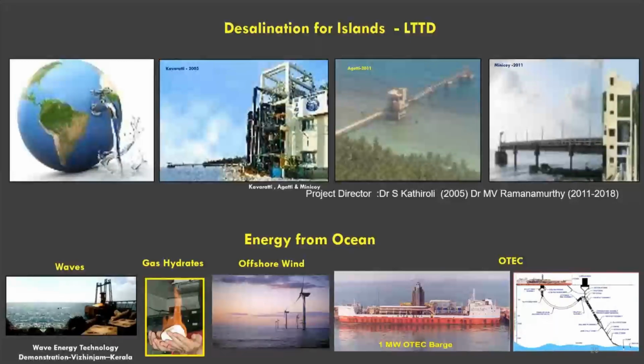One among the cases: the conventional desalination technique, you all must be knowing about, reverse osmosis. Here, close to India in the Arabian Sea, there are a few islands called Lakshadweep Islands, wherein this technique of low temperature thermal distillation was evolved. In an innovative way, the ocean at 500-meter depth has a temperature of 11 degrees. The surface sea water is vaporized using 20 millibar vacuum, and that is condensed by drawing the cold water. This is a simple technique, but more site specific, and it has been evolved, mastered and installed in 3 islands, functioning in one of the islands from 2005 onwards.